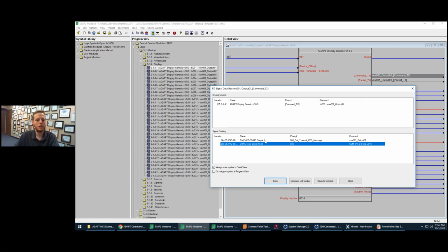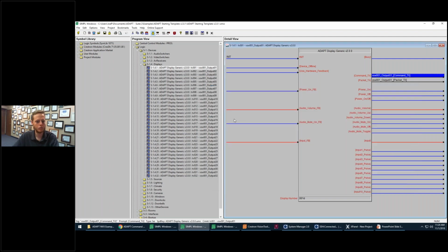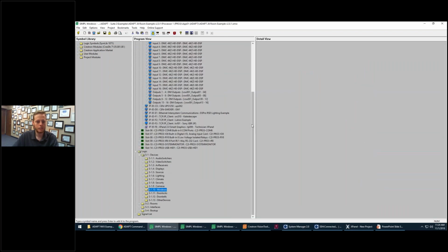And so if you're only using CEC or you're using a COM port, then you're fine. If you are intending on using maybe CEC for your TV, but the COM port for your AVR or something like that, then yes, you would want to make sure that you're handling those signals appropriately. But right out of the gate, this has no problem landing one serial signal on 2 different destinations there. Good question. Thank you for the question. Keep them coming.